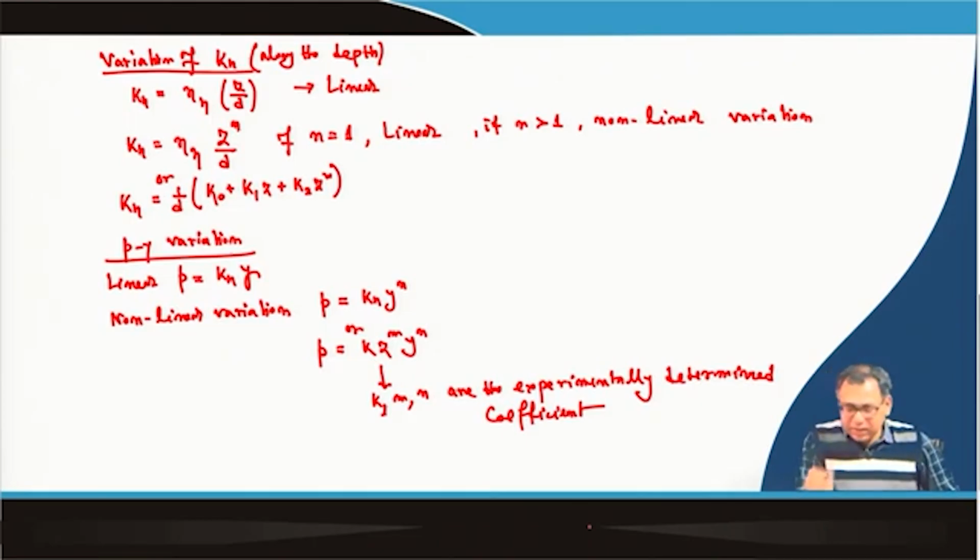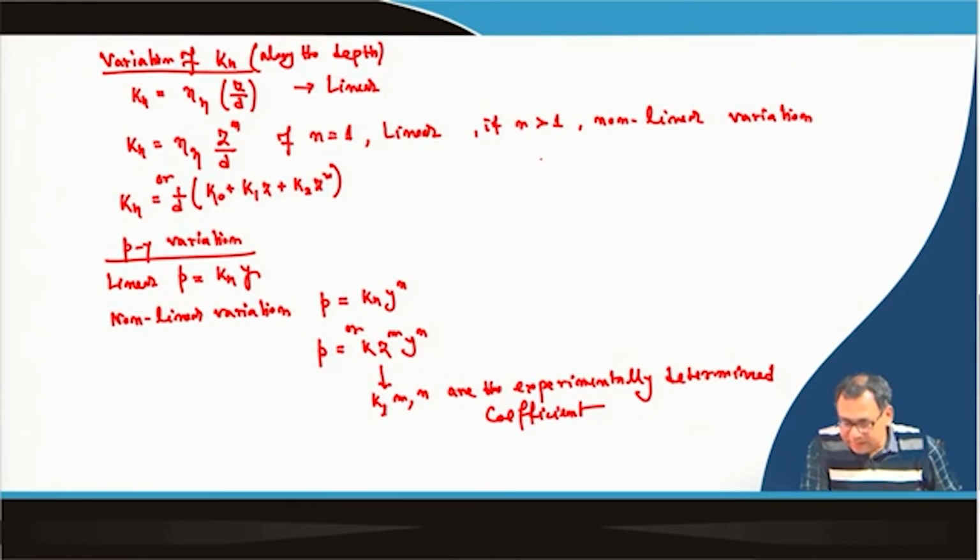Okay. And another thing is that, as you know, the kh value is not constant with depth, it is varying for this granular type of soil. So, you can vary this kh, and if you want to make it uniform, because for the cohesive soil it is uniform, then you can make these things uniform also.